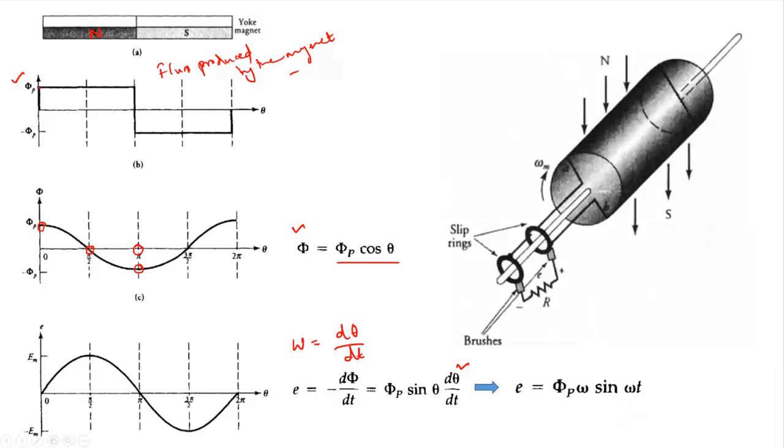Now we can see how we will collect this voltage, because the coil is rotating inside the machine. Therefore, a two slip ring arrangement is there. The slip rings are fixed to the rotor through some insulating material, so there are insulators in the inside part.